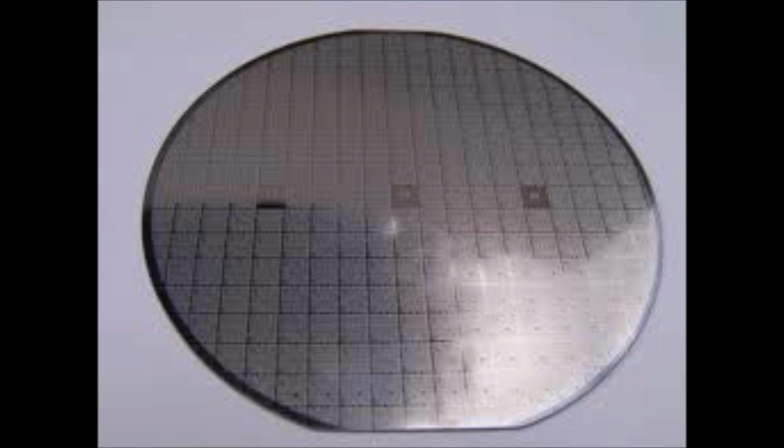And here are the results for this year's DC test, because we already passed the DC process. You can see here the gate length at point A, and we can get a GM of 360. It's just for the N channel. The P channel, we have 2 micron, that's a pretty large one, and we get a GM of 35.